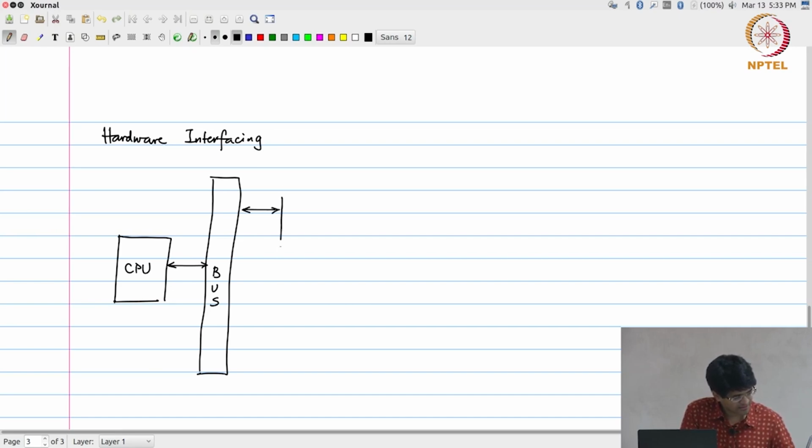On the other side of the bus is some memory, right. So, for example, the board that we will be using for our testing is something called the Z board, which is based on the Xilinx Zynq processor. Okay. So, for the Z board, this is an ARM processor, okay, the same kind of ARM processor that most of you have in your mobile phones, right, a variant of that. The memory that is available to this is around 512 megabytes, quite a decent amount of memory, much more than the on-chip block RAM that is available inside the FPGA.